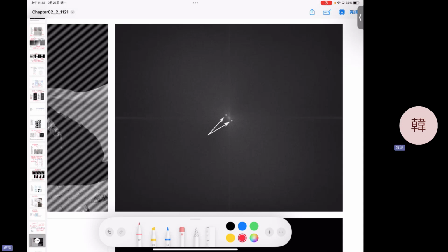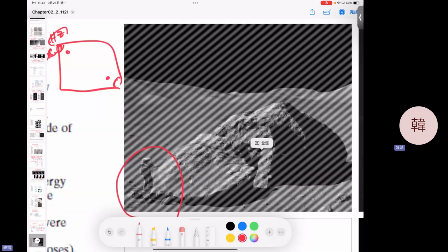And here is something repeated. What's repeated? There's some sinusoid form there. So you see this pattern? There's some frequency here. The frequency is a sine, cosine. A sine, cosine transformation in the frequency domain becomes an impulse spike. An impulse spike in the image is a shining dot point.